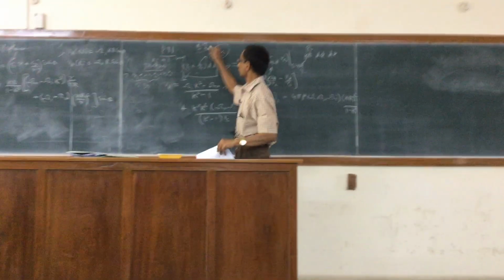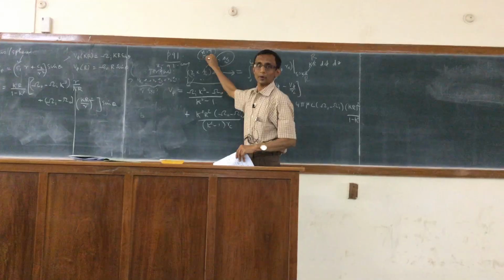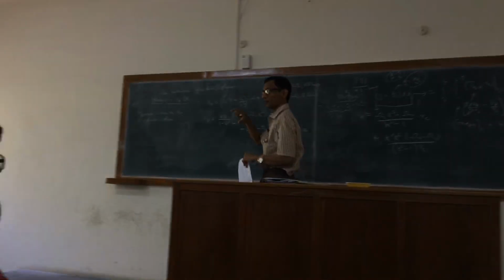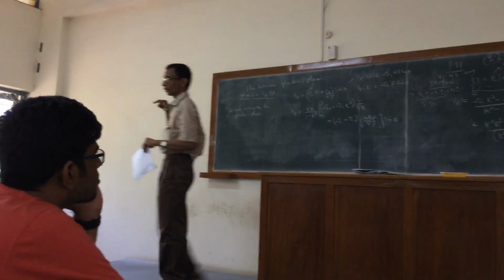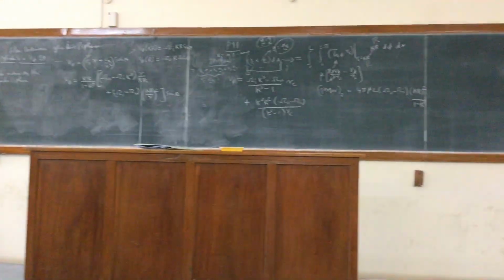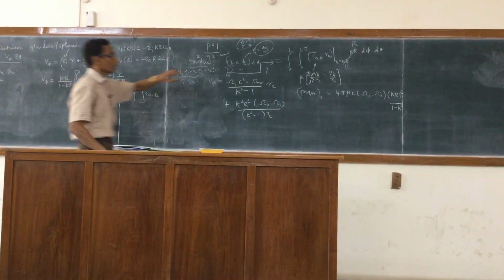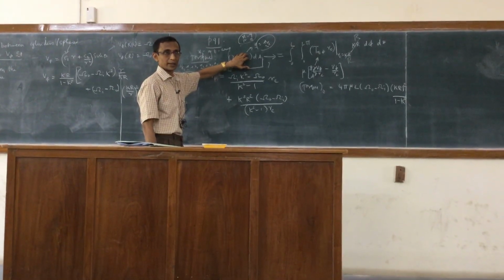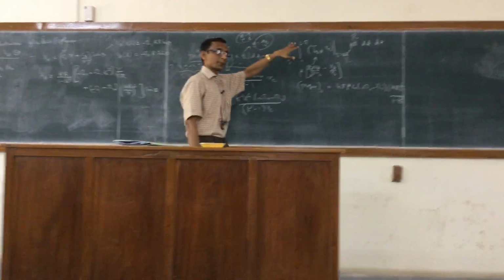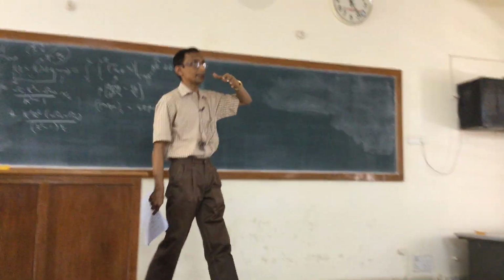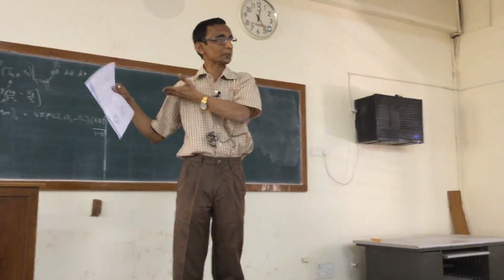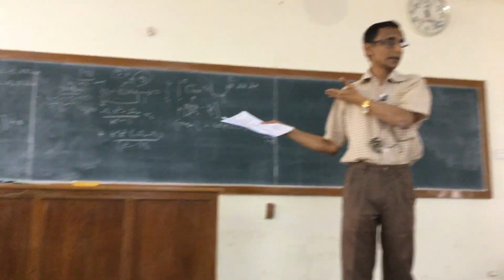Now we take the dot product with n given by e r. So you will really find that only the first row of the stress components would come in. That would be the vector T. On top of that, you have to now take the cross product of these two, right? And then you will get terms involving er, e phi, and ez in general. So the er, e phi have to be again converted to e1 and e2.